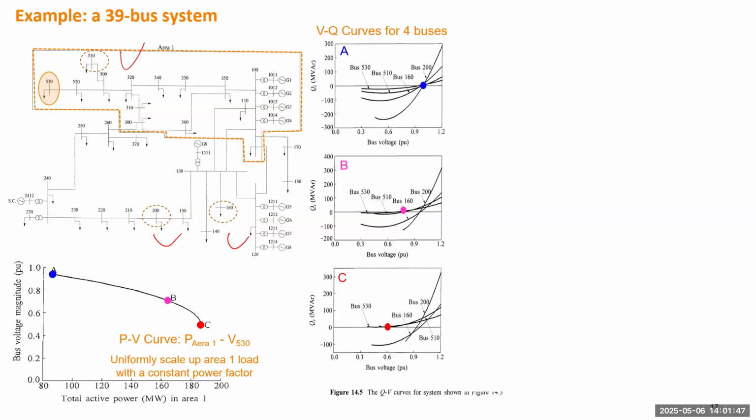So you see for the condition A, when the load is light, and so when the injection at each bus is 0, so we don't have any control. And this horizontal line will intersect with VQ curve, right, at this point. And the slope all positive at that point. So which means the system is stable. So that is also confirmed from this PV curve.